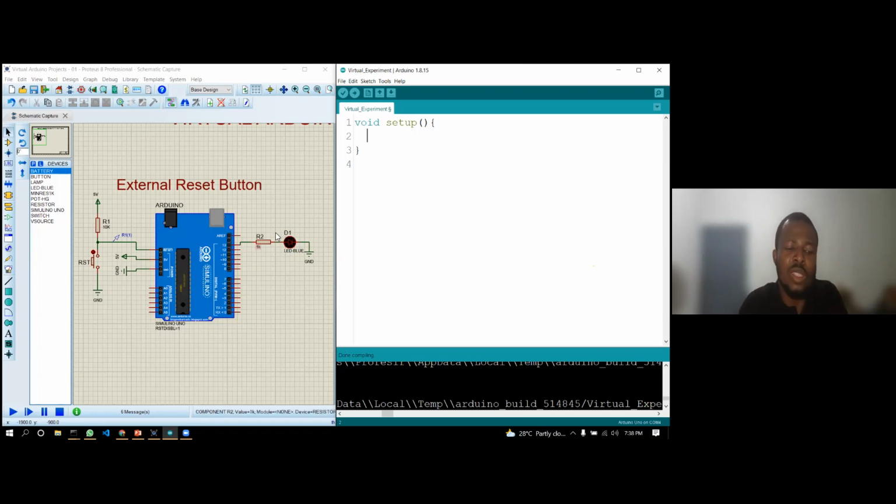So in order to deal with the excess voltage, we put a resistor here, and the resistance value is calculated so that it can deliver the current that we want. Now, in this case, let's assume we want 10 milliamps of current to flow through the LED. That is possible because we know that the Arduino pin can supply 20. So if we only need 10, that is good news, right? Because yesterday I told you that you should never draw more than that current. Okay, so 10 milliamps is good.